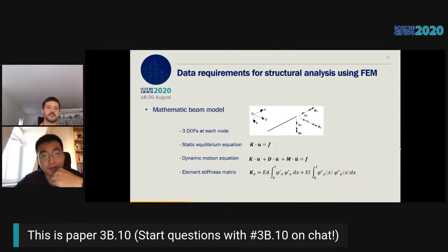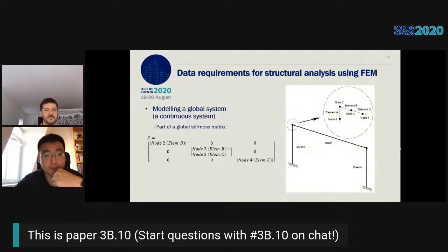Now we are going to check the finite element system. For static structural analysis using FEM, stiffness matrix K is the most important factor. The last equation shows how element stiffness of a beam in its local coordinate system is defined. And finite elements are obtained by meshing a structure. After meshing, continuous modeling of finite elements are realized by coupling through nodes. Therefore, a node is supposed to contain all parameters of related finite elements.